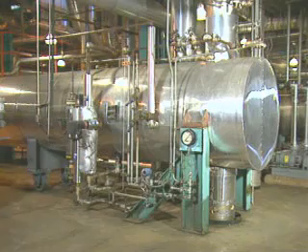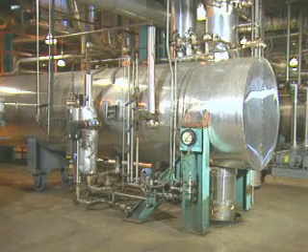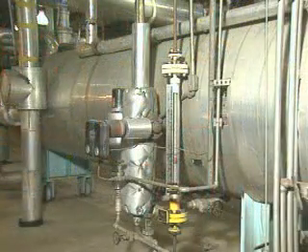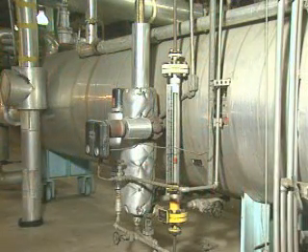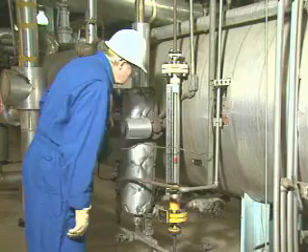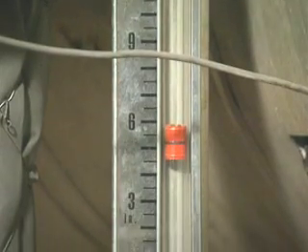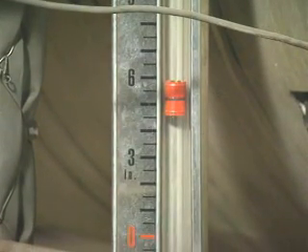We'll look at some operating checks for a high-pressure closed feedwater heater. Most of the checks for this type of heater also apply to low and intermediate pressure condensate or feedwater heaters. To monitor the level in the shell side of the heater, you can usually check a sight glass on the heater. An abnormal level in the sight glass could indicate a problem that should be reported.